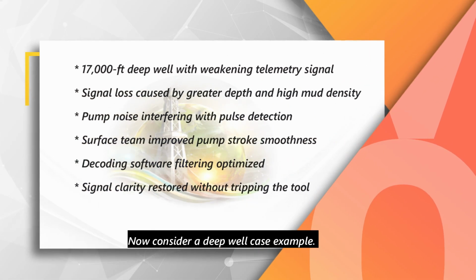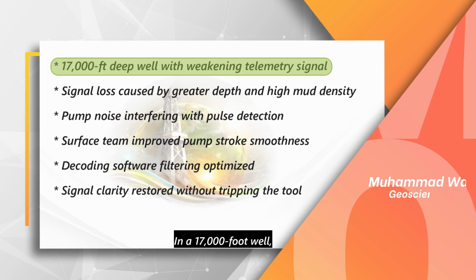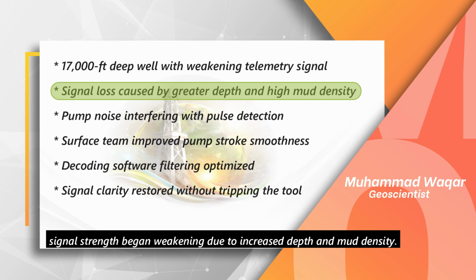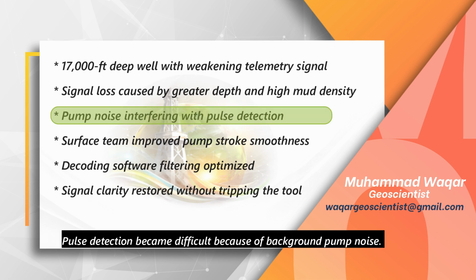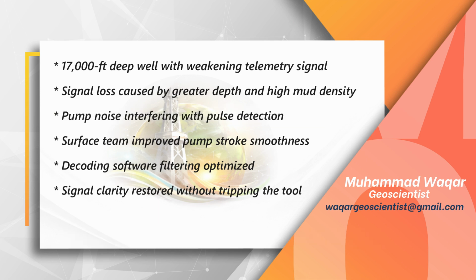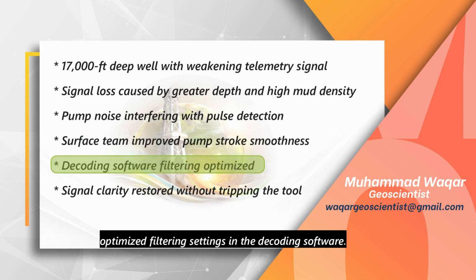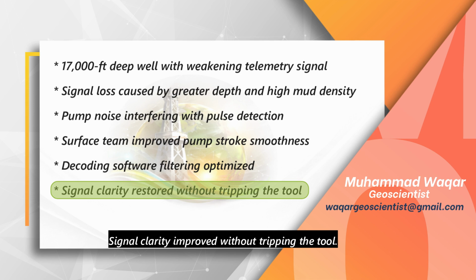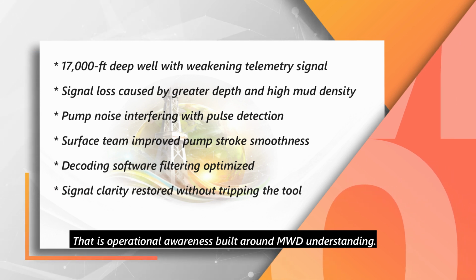Now, consider a deep well case example. In a 17,000 foot well, signal strength began weakening due to increased depth and mud density. Pulse detection became difficult because of background pump noise. The surface team adjusted pump stroke smoothness and optimized filtering settings in the decoding software. Signal clarity improved without tripping the tool. That is operational awareness built around MWD understanding.